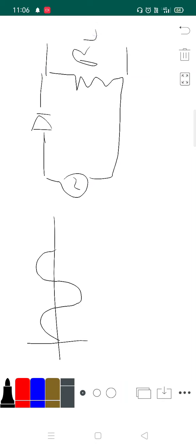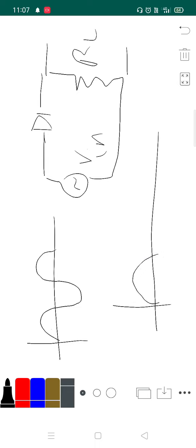Okay, this is RL, this is the diode, this is the PN junction diode, this is the voltage Vin. The output waveform of this rectifier is you will get only positive half cycles, because this diode is connected in the forward bias condition. When the diode is connected in the forward bias condition, you will get only the positive half cycle. The negative half cycle will be rejected.